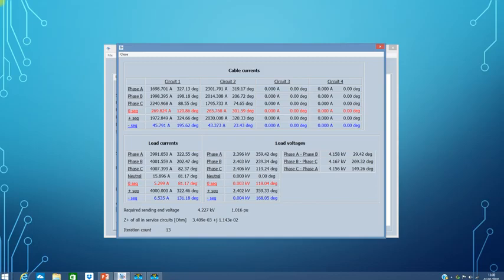Now, we've spoken about taking the symmetrical components of the currents in each circuit. The symmetrical component transformation is simply a change of reference frame, and the presence of negative sequence and zero sequence currents can be used to identify the presence of unbalance on a power system which might occur, for example, during fault conditions.